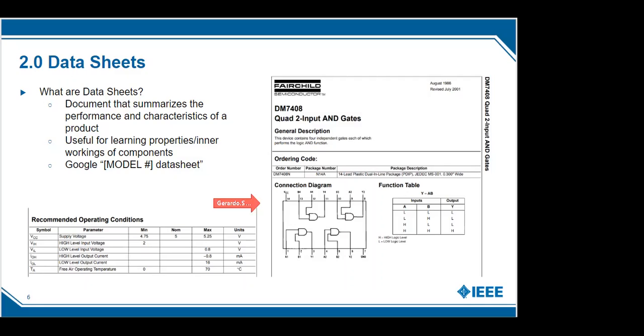So it's important to look at your data sheets when you're working with IC chips in order to make sure that you're making the right inputs. And normally right here we have a VCC, which is for our power, and our ground for our chip. If you don't make those connections, what you'll find is that your chip just doesn't have any power and it's not going to work the way you want it to. So we can go on to the next one.